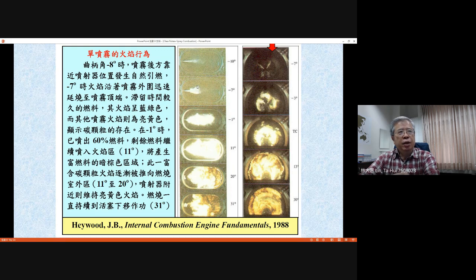In this region, droplet size is small and there is strong mixing with the high temperature air. Then the ignition will be started by this high temperature environment. The chemical reaction proceeds. As you ignite the spray, the spray is coming out continuously, right? More diesel fuel will come into the combustion chamber.